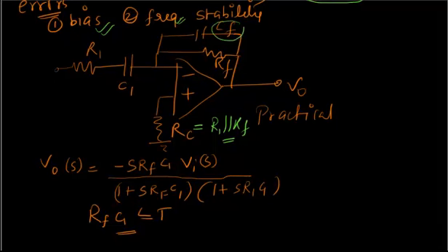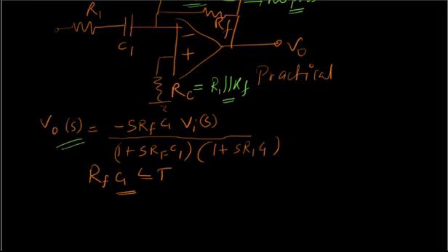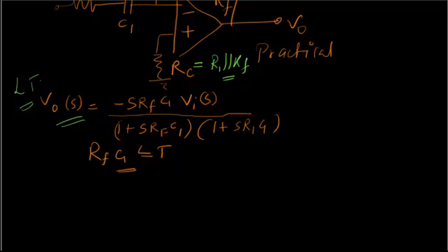What this CF does is it bypasses the AC components, so that no problem of high gain for large frequencies. Remember it just as the opposite of the integrator. And this will be your transfer function in S domain, which is nothing but the Laplace transform of your time domain. Now one more thing, here this is the time constant in case of differentiator.